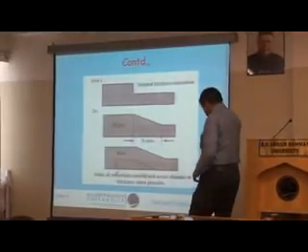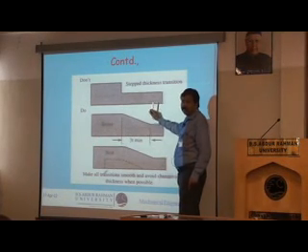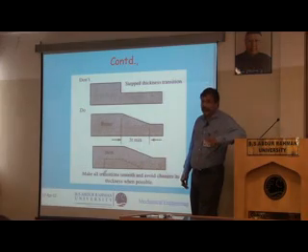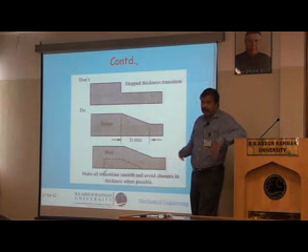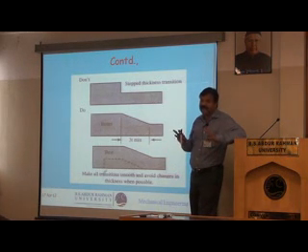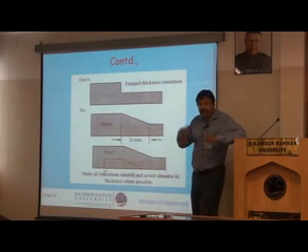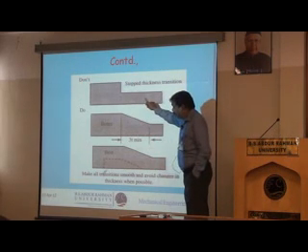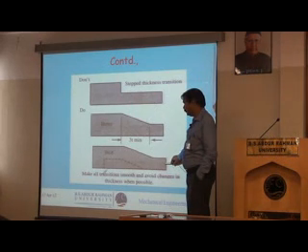Now, similarly, don't change the cross section suddenly. Later on, you will study a phenomenon called stress concentration, wherein again a sudden change in cross section is not at all preferred in engineering. In engineering, you never change the cross section very suddenly. A gradual change is always preferred, even from the stress point of view. Now here again, this you should never do. This is much better. This is best.